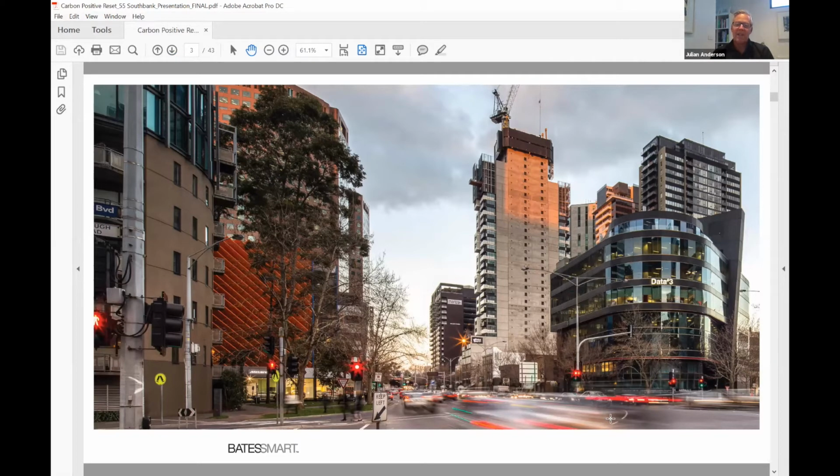And the existing structure was designed to take 5 or 6 levels of new concrete structure over, but using cross-laminated timber, we were able to deliver 10 levels of new structure, which has allowed us to deliver 220 hotel rooms, which is the optimum number of rooms for a hotel development of this type. So this is now one of the largest timber adaptive reuse projects in the world, delivering 13,000 square metres of new floor space.